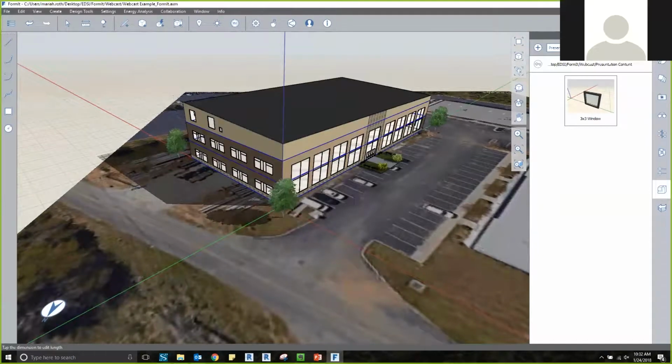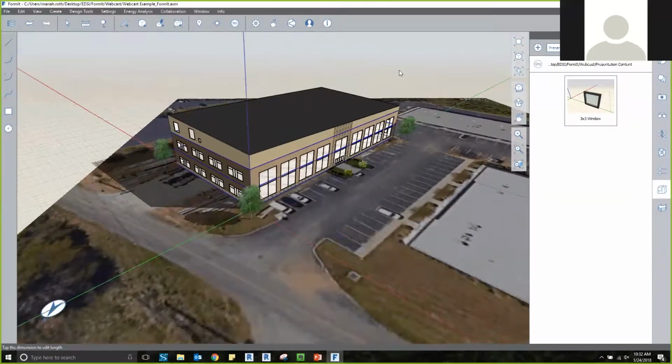I think that part right there is very compelling because as you're doing your conceptual design, no matter what you're doing, whether it's a commercial building, a school, a house, there's always going to be content that you're going to need in order to help put these things together. Certain content is going to be somewhat common, like doors, windows, furniture. And I know Mariah is going to continue on with her presentation, but when it comes to windows, non-hosting elements cannot be transferred over. So you will have to develop that content, and it's reusable. So no matter what you create, you can use it on other projects.